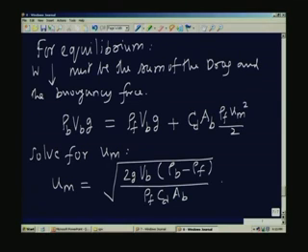So, what does it mean? It means that the velocity cannot change, whatever may be the position of the bob. Equilibrium requires that the u m is a constant. That means, if I am allowing a certain amount of fluid to flow through the system, it will decide the position along the length of the taper tube where the value of the velocity in the annular region between the bob and the outer tube will be exactly equal to u m. So, the equilibrium position will be determined by the requirement that the velocity u m be a constant given by this particular quantity, assuming that C d is a constant.